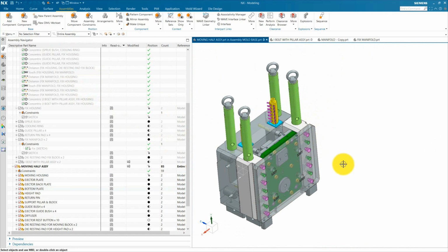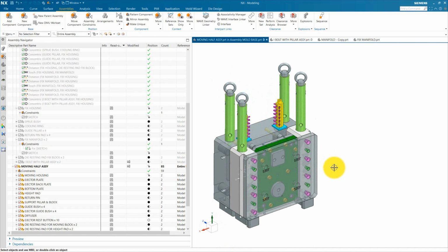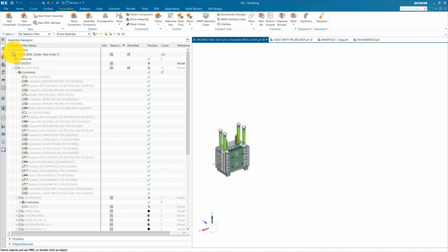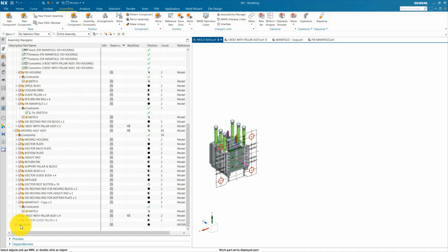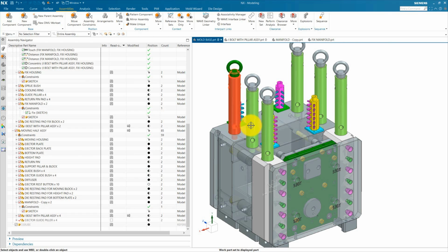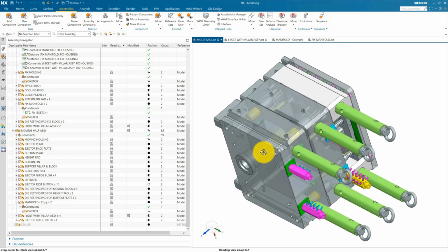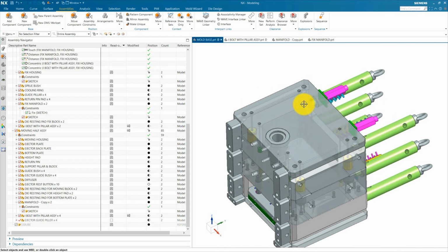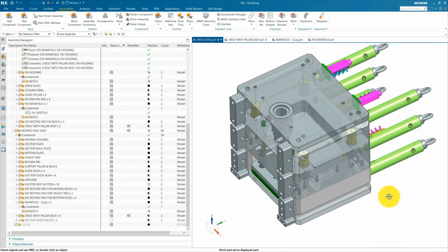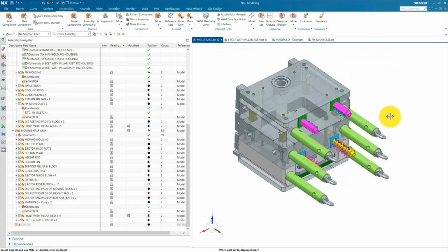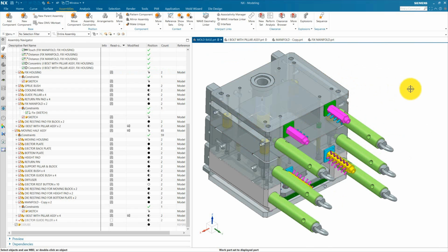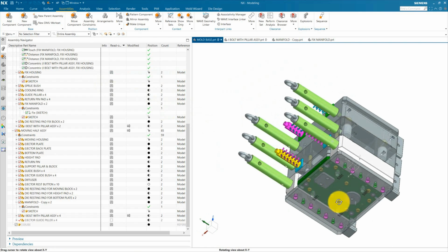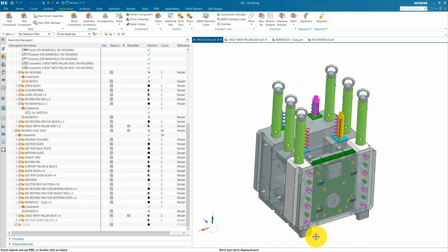Now our lifting pillar is assembled inside our fixed hub assembly and moving hub assembly. You can see our standard mold base is approximately complete. Now in the next video we are going to talk about the standardization of mold base. For different tonnage of machine we use different thickness for our guide pillar and guide bores and the thickness of our moving housing and fixed housing. So that we will discuss in the next video. For this video the standard mold base is completed.